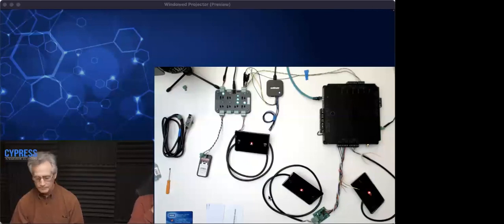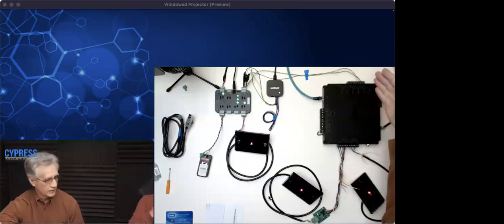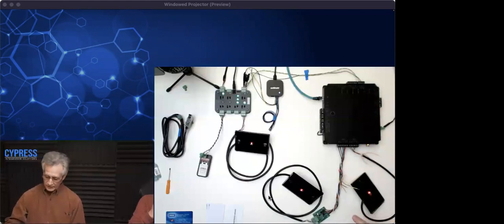Excellent. Can I use the OSDP converter with a Wiegand reader? And if so, will it be secure? Okay, so going the other way, if you have a Wiegand reader outside of your door, and you want to go to an OSDP panel, for example, yes, that bit of wire is vulnerable.